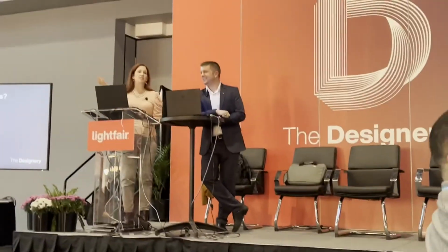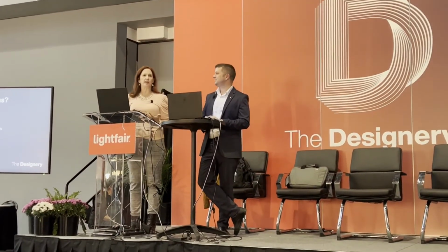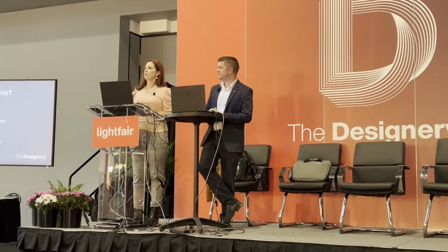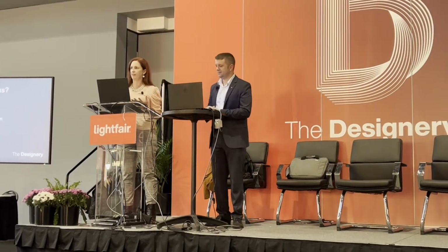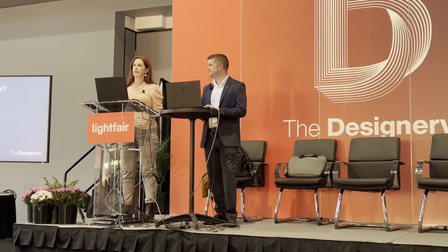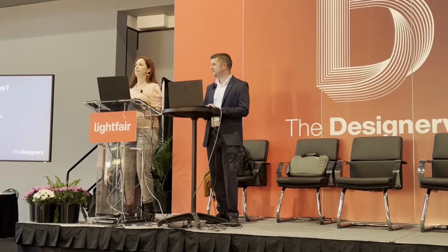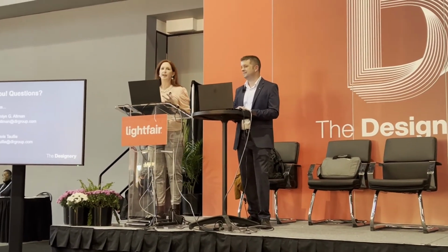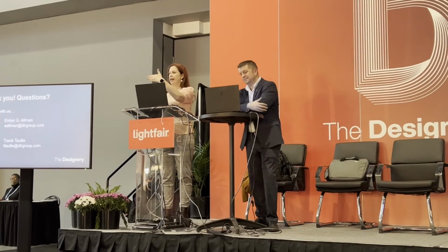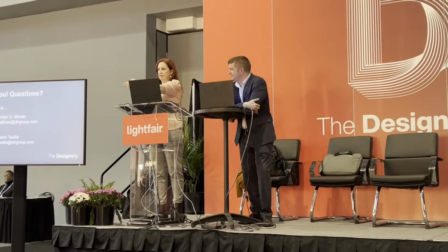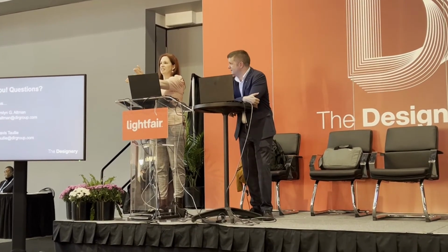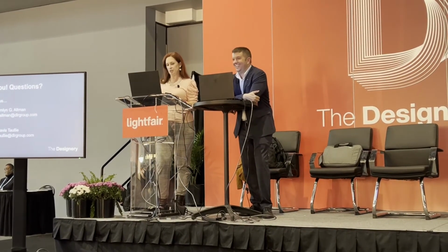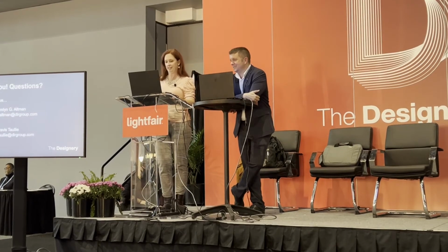But I will say, for the work I've been doing, LightStanza has really helped, because one of the things that I've struggled with in Revit is that if the model's not perfect, if it's not built well, if the families aren't well built, we've had issues where you have a pendant that's one way and the photometrics is perpendicular to it, or it's like 2 foot below. And actually, I can probably show that right now if you don't mind.